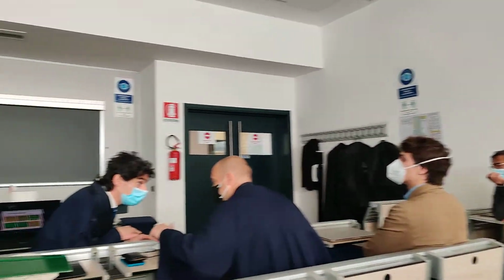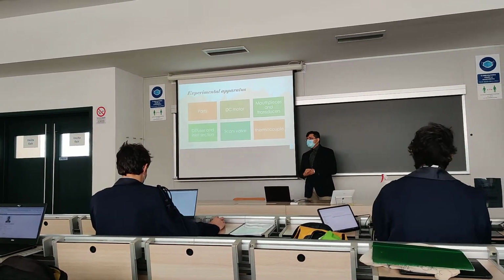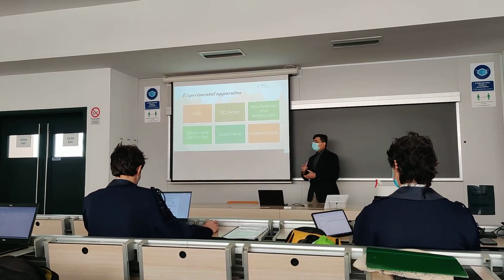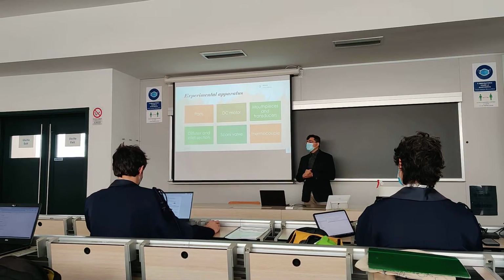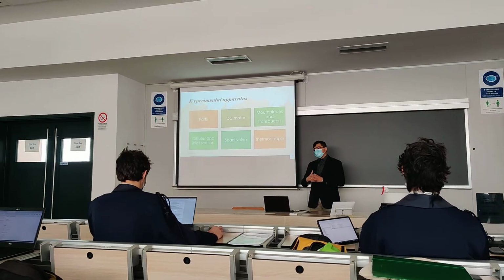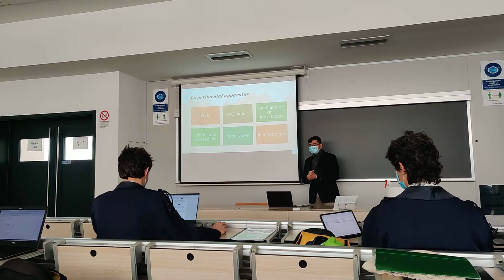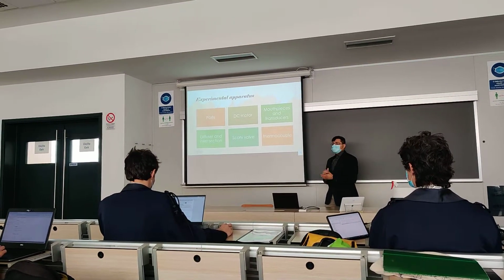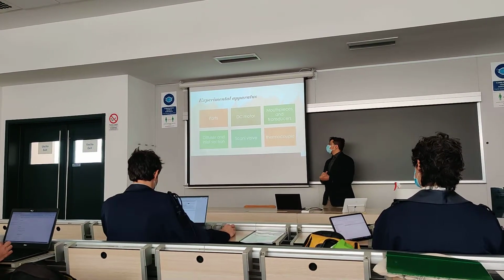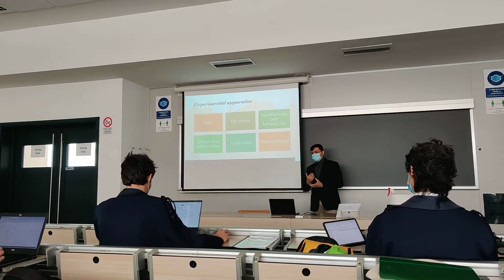And then come mouthpieces and transducers. The mouthpiece works with the orifice principle, that is differential pressure. It creates differential pressure between the atmospheric condition and the inside, so the air flows from a region of high pressure to low pressure. Then the transducers. Transducers are an important part because they help in the conversion of physical signals into digital values.